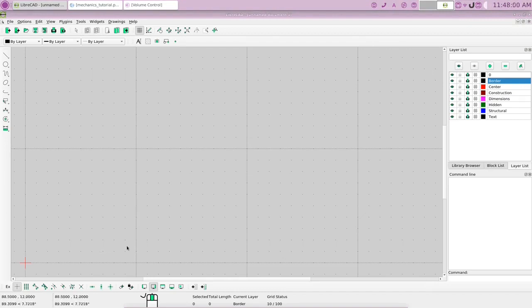But you will remember the A4 paper drawing is 210 in the Y by 297 in the X direction. So our border wants to be in from the edge of the paper. Maybe at least 5 mils in all the way around. So if you have 5 mils in here and 5 mils in here, that's a total of 10 mils you're taking off of the X direction. So instead of 297, our border would be at 287. And height is 210, but it will actually be at 200.